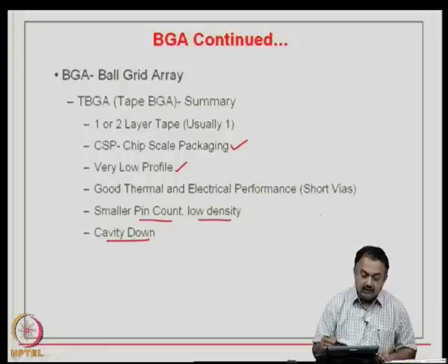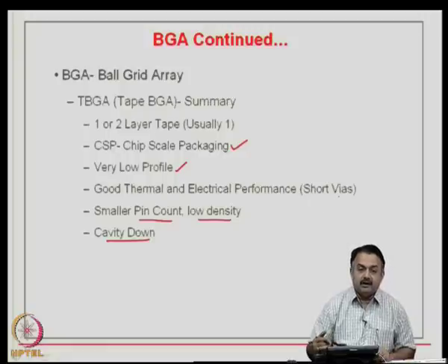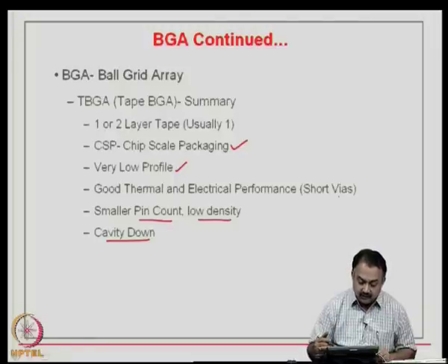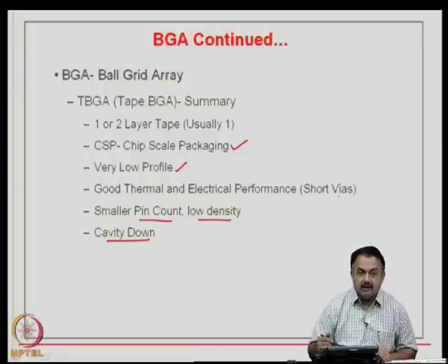So, basically you can expect the features to be available on a tape, and then you have the bonding taking place between the die, and the ball grid array typically comes in a tape format. Typically a tape ball grid array is not very common nowadays. Most people use plastic ball grid arrays, and for high end applications we use a ceramic ball grid array.